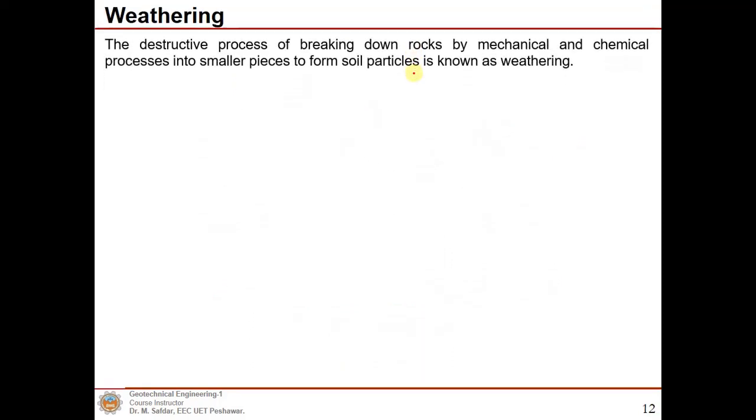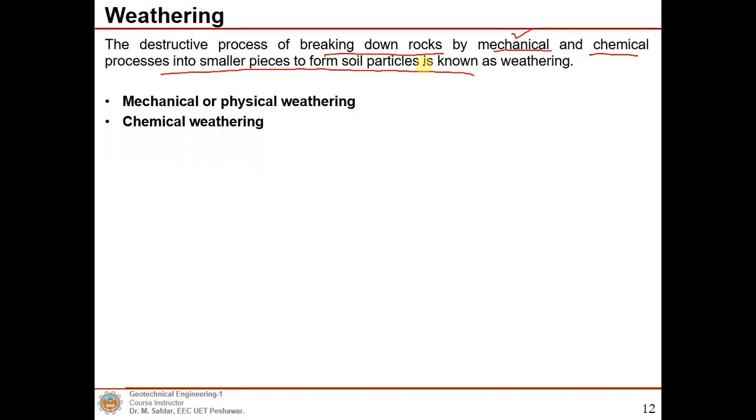Now, what is weathering? The destructive process of breaking down rocks by mechanical, physical and chemical processes into smaller pieces to form soil particles is known as weathering. We can divide weathering into mechanical or physical weathering, and chemical weathering.